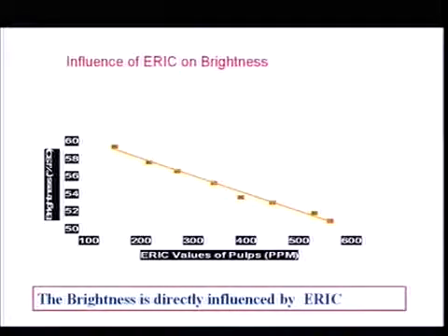For example, 600 ppm here, you can see the brightness of that newspaper is very low. As you remove ink in your flotation cells and washing devices, you are lowering the ERIC, less residual ink is present on your paper, you are brightening the fiber. Okay. Why is ERIC important in bleaching?